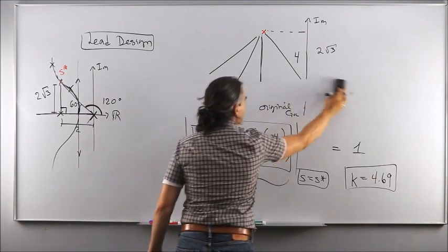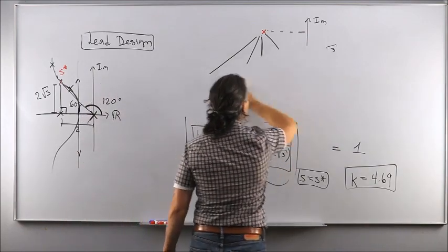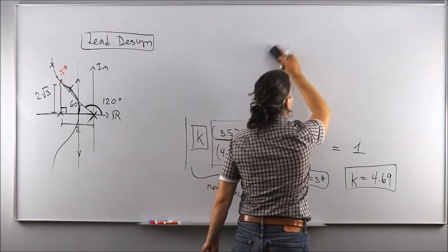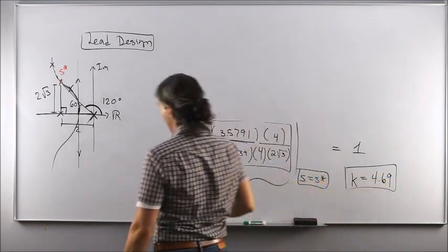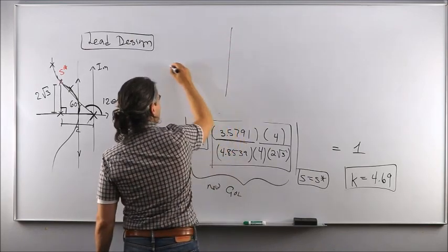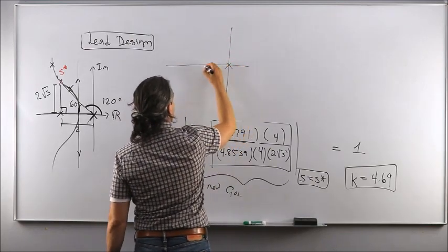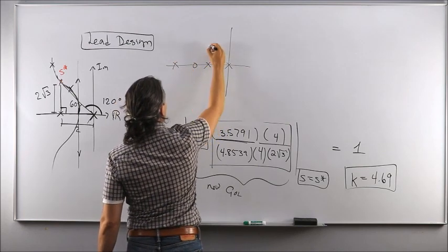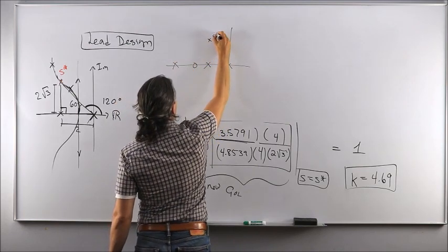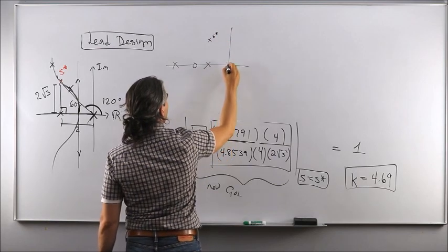And guess what? By cranking the gain of the open loop transfer function, the new one, to exactly this, you will end up with your poles going right through S star and ending up there.